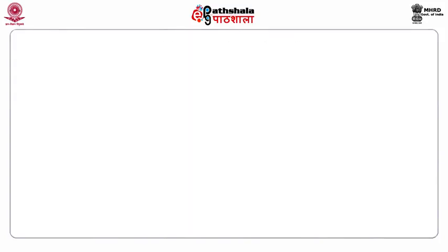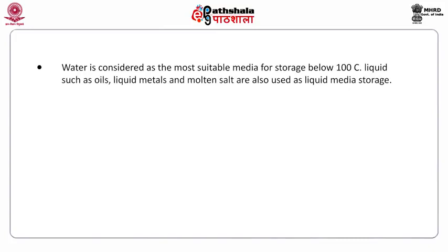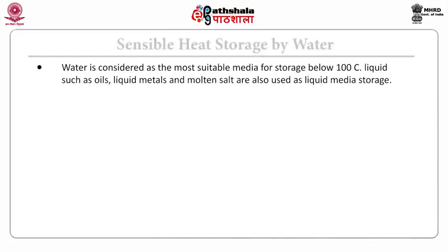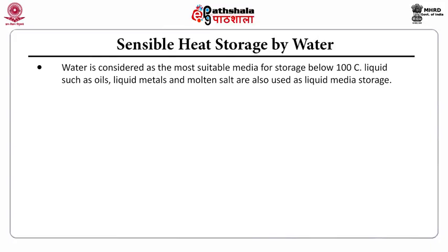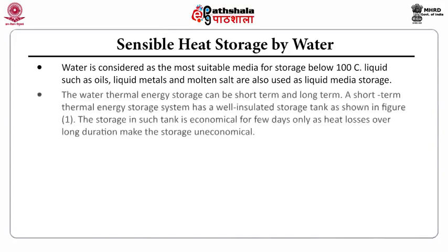We will see the sensible storage of heat by water. Water is considered the most suitable medium for storage below 100 degrees Celsius. Liquids such as oil, liquid metals and molten salt can also be used as liquid media storage. The water thermal energy storage can be short-term and long-term.